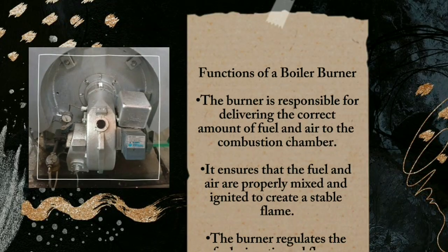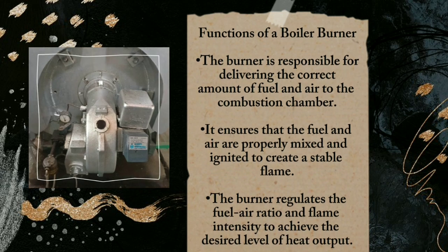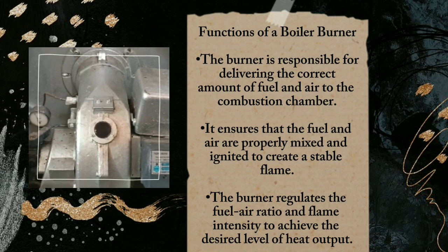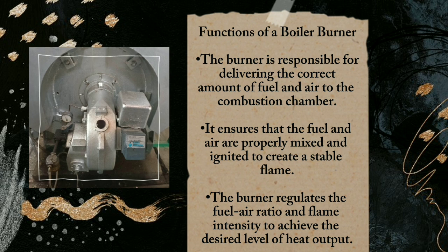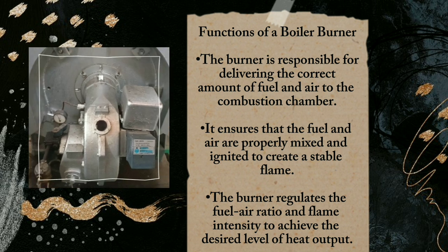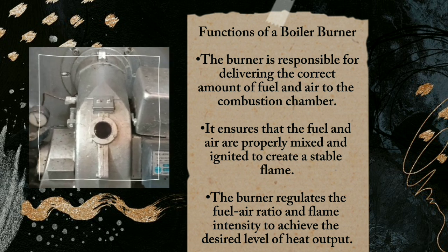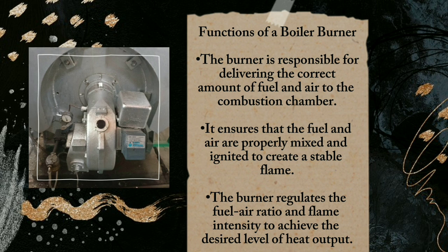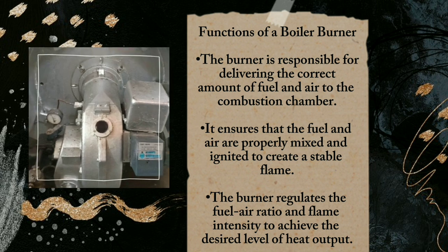The burner is responsible for delivering the correct amount of fuel and air to the combustion chamber. It ensures the fuel and air are properly mixed and ignited to create a stable flame. The burner regulates the fuel-air ratio and flame intensity to achieve the desired level of heat output.